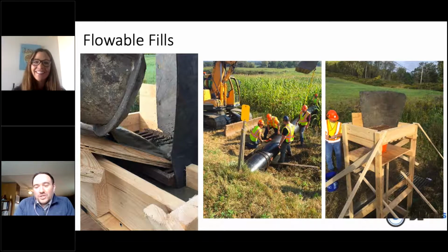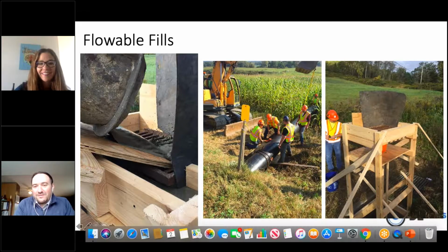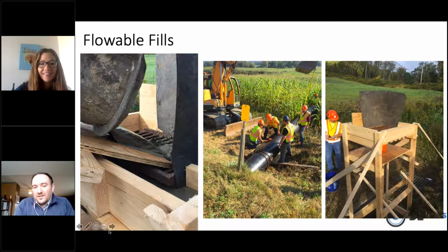So on the right-hand side picture, before she shows this video to you all, you're seeing basically just plywood 2x4 and a little bit of orange. That's an upside down traffic cone with a catch basin grate on top to catch any solids coming off the truck that they don't want going into their PVC. And you can go ahead and click that.